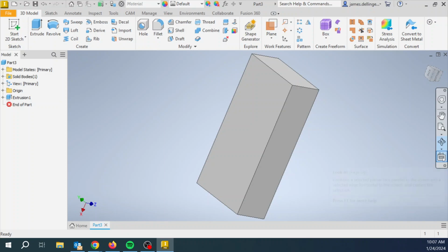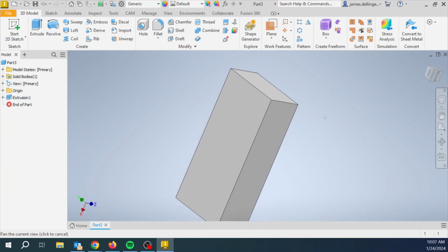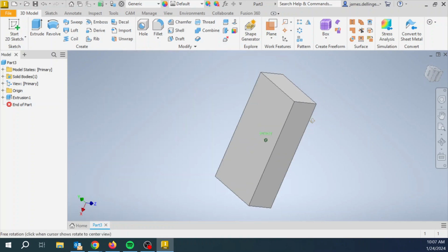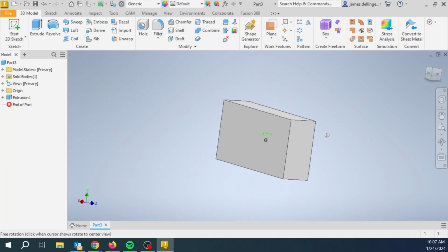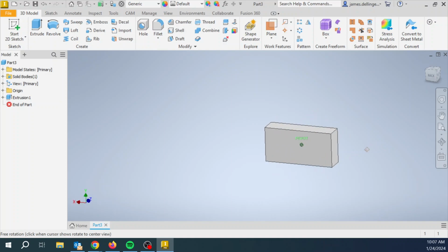And then I don't ever really use the look at too much. You can learn how to do that. All right, so that's 3 different ways to do the same thing. I prefer the mouse, middle mouse pan, zoom in and out with the middle mouse, and then shift middle mouse, because it keeps my hands, I don't have to move and click anything. It's a lot quicker. Okay, but you do whatever works for you.